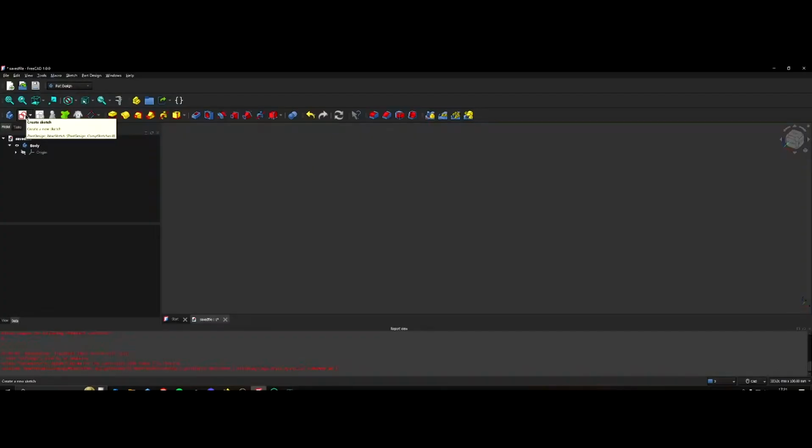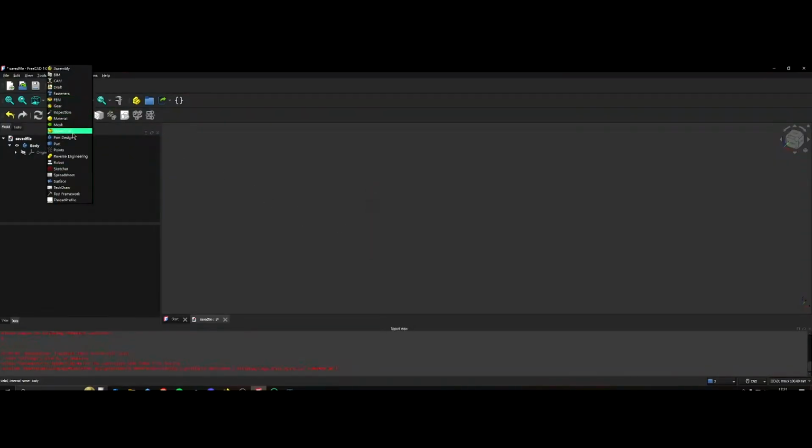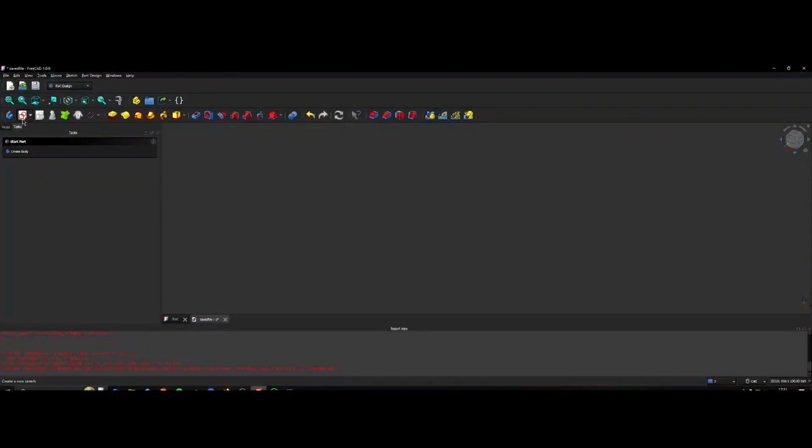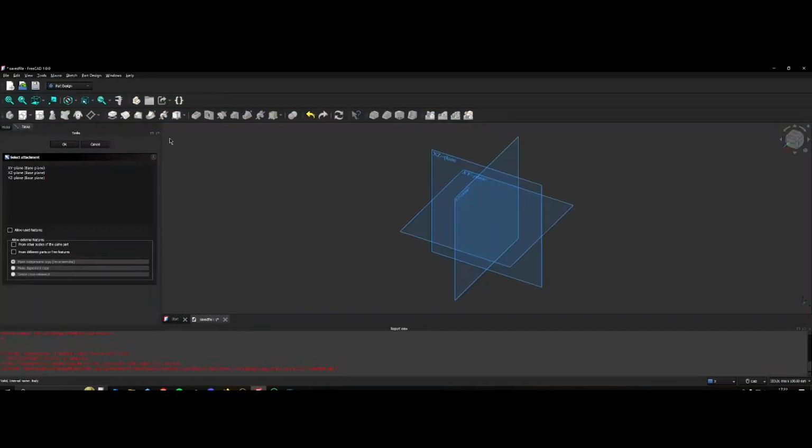The vast majority of FreeCAD projects start with sketches, which will map out the geometry of the object you want to extrude, pocket, etc. To create a sketch, you can either navigate to the Sketcher workbench and click Create Sketch, or you can find the same button located within the Part Design workbench. Just make sure that when you create a sketch, the body you are creating it within is active.